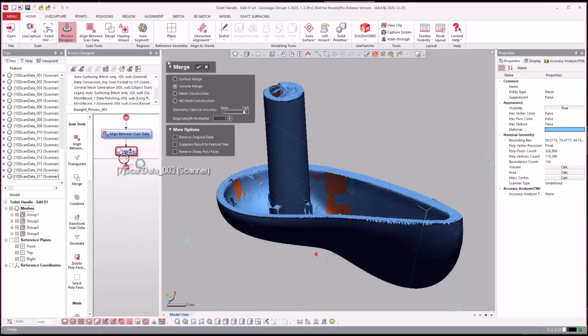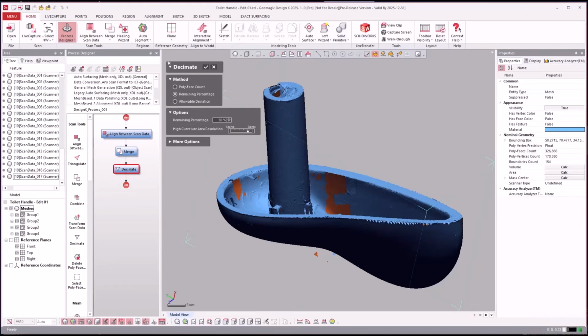Then we'll come over to decimate, and we'll hit keep. I'm supposed to hit the checkbox up here, so I'm not doing that. I'll show it properly next time. I'm going to say decimate, no matter what it is, decimate it down to 1.5 million points and crank it to 11. And then you see here, I'm saying every time do it to a static polyface count.